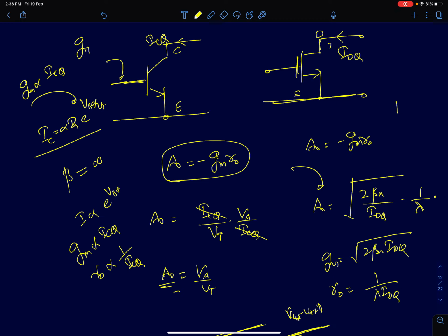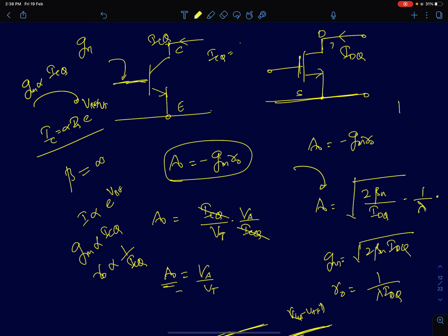If you recall in the previous lectures, when we compared BJT and MOSFET very briefly, we said a MOS device has a higher transconductance for the same drain current. Meaning if I equate the collector current to the quiescent drain current, if I choose the same currents, a BJT is going to offer you a higher transconductance, because that comes from the exponential versus square law characteristics.